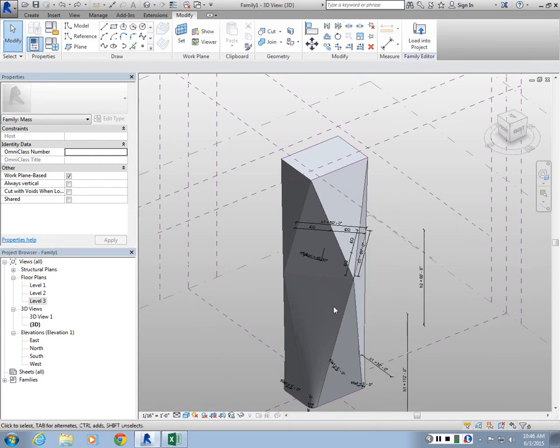So tomorrow I'm going to show you how you can also use these surfaces to derive patterns on them and do adaptive components, because most of these are three-dimensional surfaces. They won't behave like curtain walls. Curtain walls are two-dimensional, or like they're at an angle, maybe tilted. But when you have a ruled surface like this, you need to do a parametric element for it.